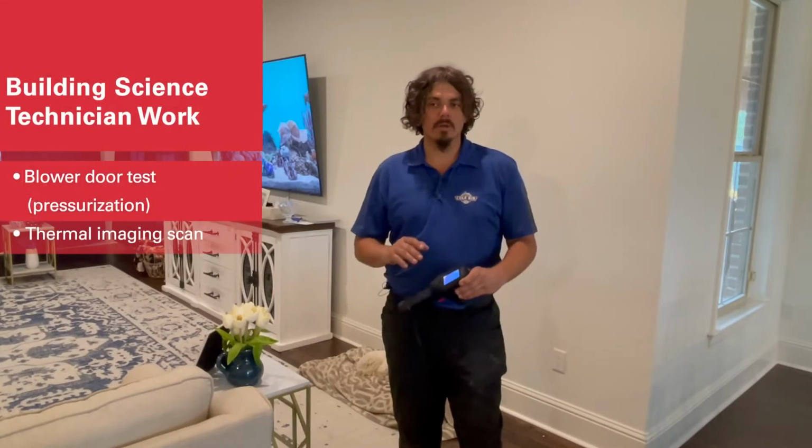All right, so we've run the blower door test. We've confirmed that the house is relatively controllable as far as air tightness goes. That's our air barrier. Now we're going to look at our thermal barrier, because from the building science standpoint, I want to ensure that once we've resolved all of this HVAC related leakage, and we send that air to that room, we're actually able to control that room's temperature. We won't be able to do that if it's not insulated properly.